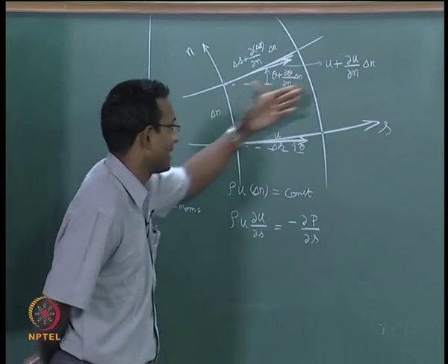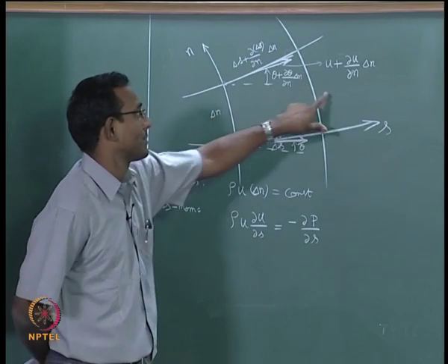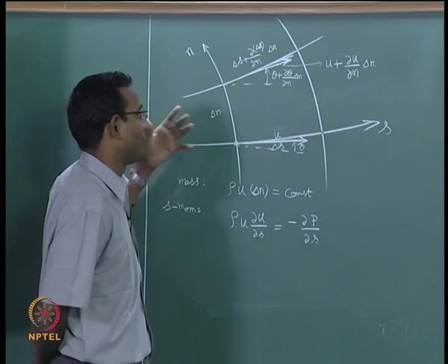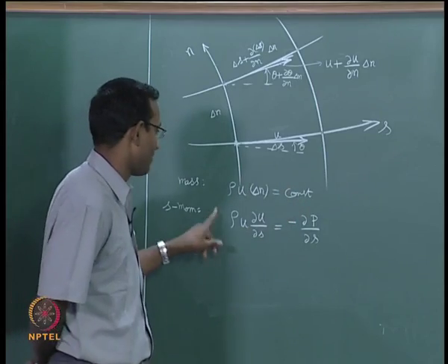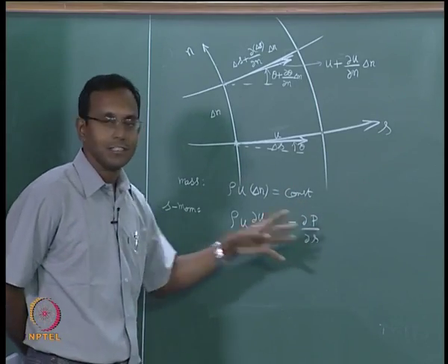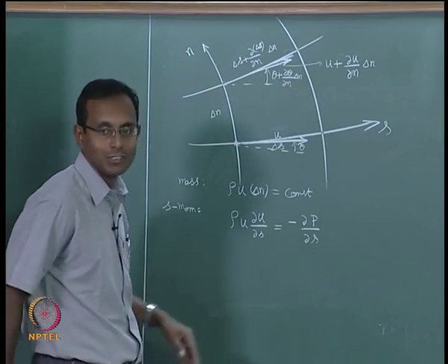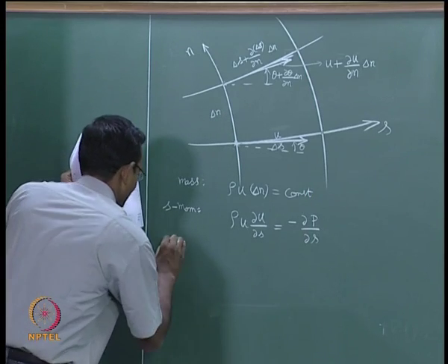The fluid is accelerating this way because I am going to say pressure here is higher than pressure here, so there is a dp/ds that is negative, and what is the net force acting? That will be minus of dp/ds times that area. I have divided by area throughout, that is this. This is basically your force balance. Momentum increase is equal to the force, that is what is written there. Or you think about it as an F equal to ma kind of formula.